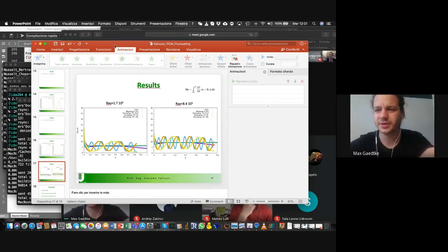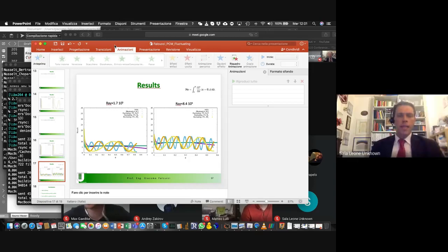It doesn't have to be, but I saw strange effects for the very first and second cell in the lattice Boltzmann grid next to the boundary. The non-equilibrium parts are ill-defined through improper handling of boundaries. Okay, we have done the Nusselt number evaluation in different stages close to the different lattice points close to the hot wall, and we see this amplification as well, but we will double check this and make sure that it is not related to the boundary condition, of course.